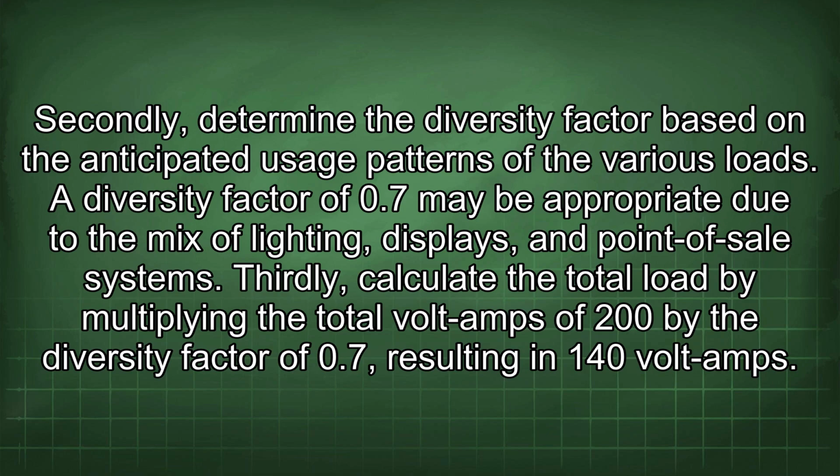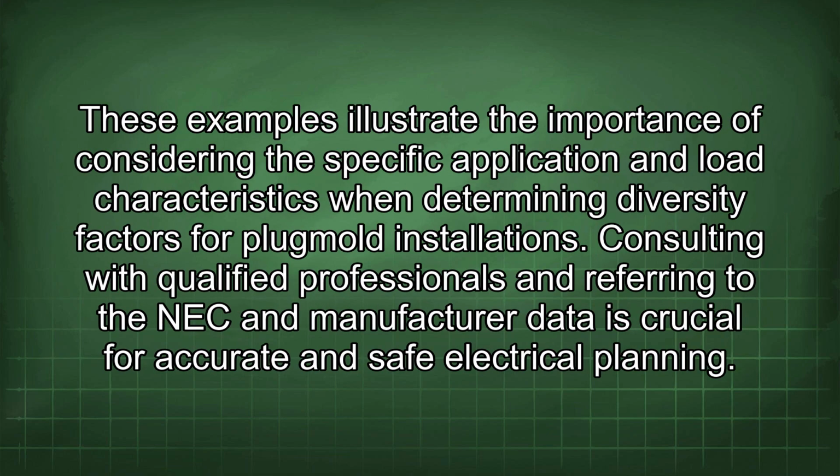Thirdly, calculate the total load by multiplying the total volt-amps of 200 by the diversity factor of 0.7, resulting in 140 volt-amps. These examples illustrate the importance of considering the specific application and load characteristics when determining diversity factors for Plugmold installations.